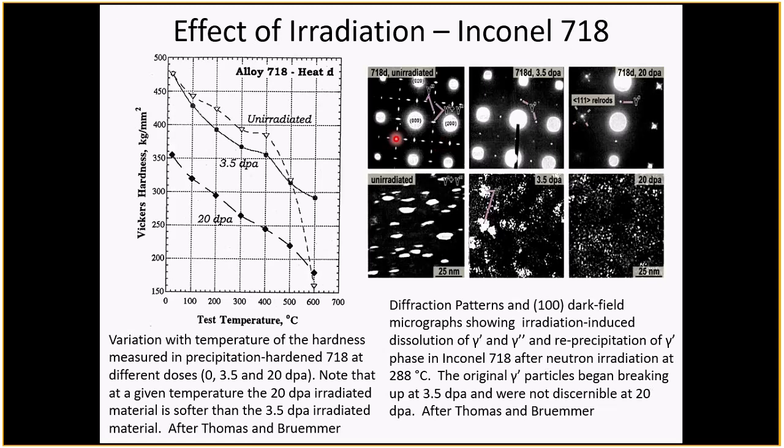And at this point, thermodynamically, because diffusion is so much quicker at the high temperatures, thermal diffusion is so much quicker, the material can reform the gamma prime phase. So there's no difference. The hardness drops anyway because that's what happens at high temperatures. The material becomes softer.